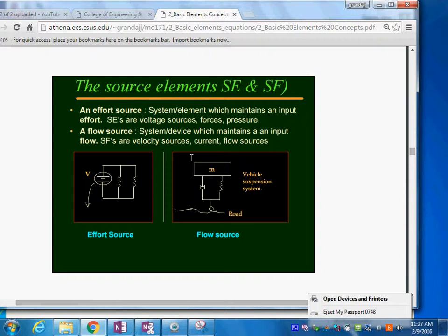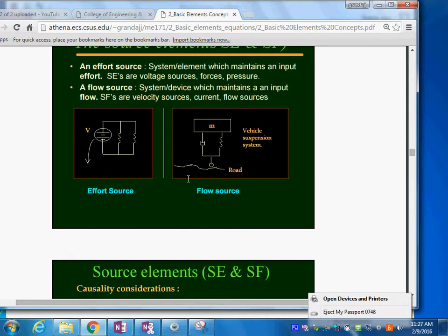It is the velocity input. Why is that? You say, how come, if I go on a bump, I feel the bump. But think what's going on physically. The tire has to follow the profile of the road, and it's going to go up and down. How's it called? The change of the position as a function of time? The truth is called velocity, right?